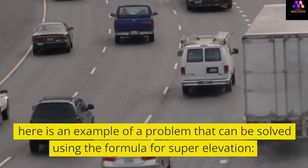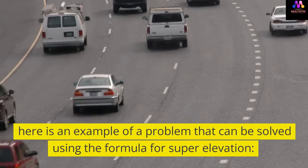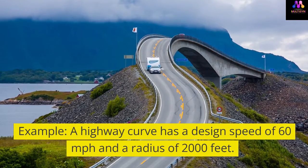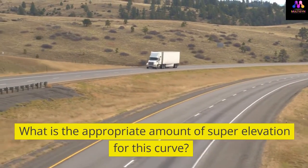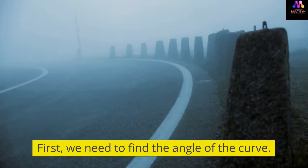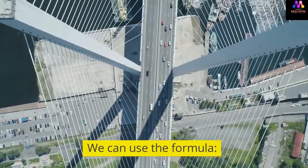Here is an example of a problem that can be solved using the formula for superelevation. Example: a highway curve has a design speed of 60 miles per hour and a radius of 2,000 feet. What is the appropriate amount of superelevation for this curve? Solution. First, we need to find the angle of the curve.